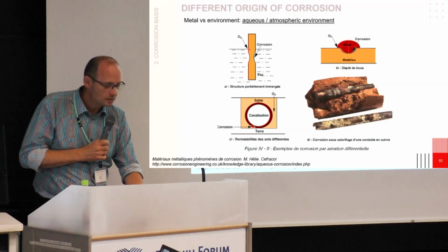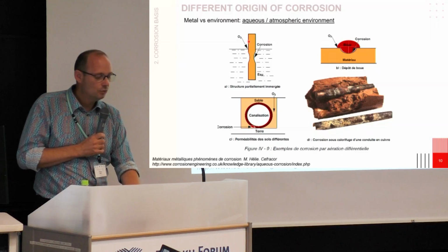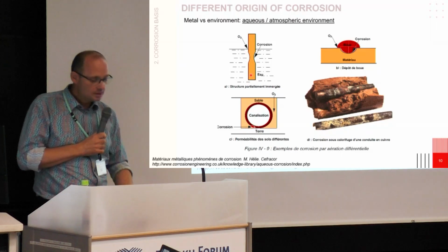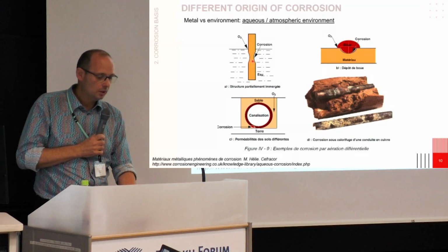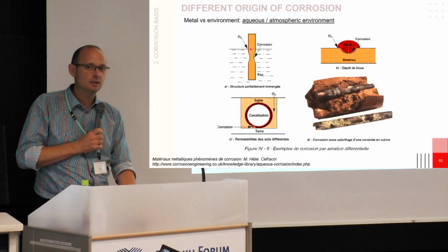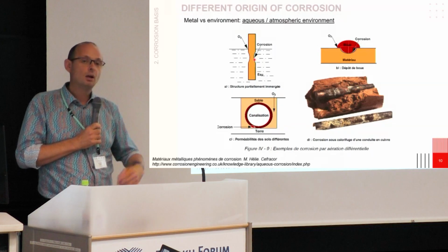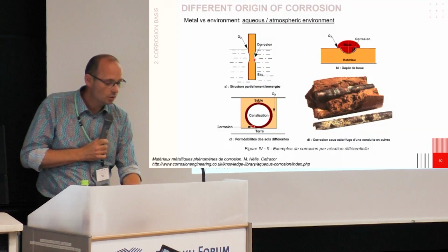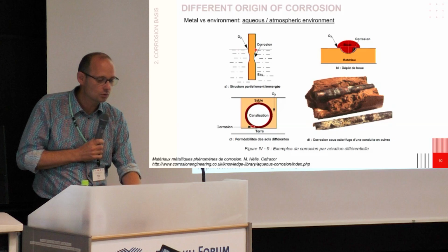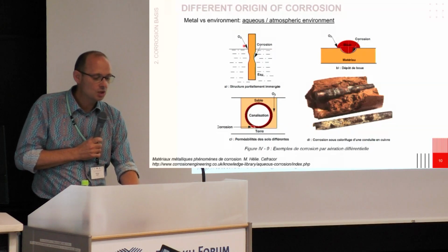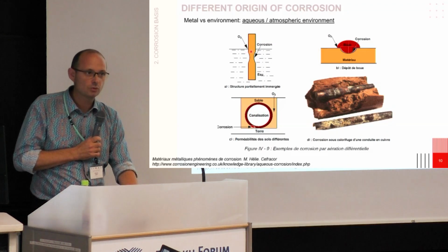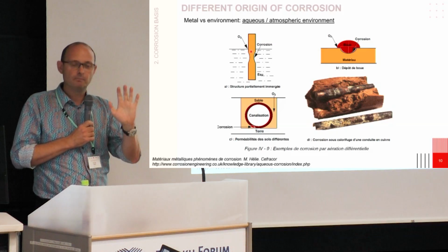And here is an explanation about that. If you put a steel rod, for example, in water, you will see that the corrosion of the steel rod will not appear at the water-air interface, but below this interface. It's only because oxygen concentration is located on the surface of the material. Oxygen exchanges from the atmosphere to the water, and because it is in the water and there are electrons close by, they react, and that's it.